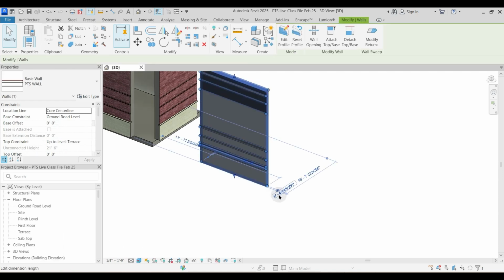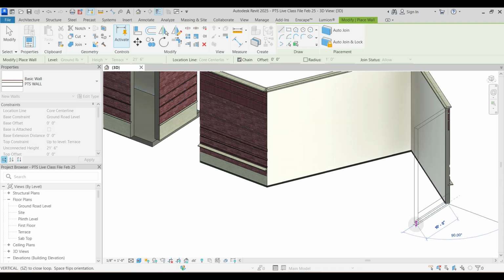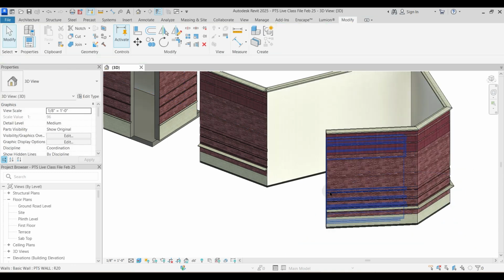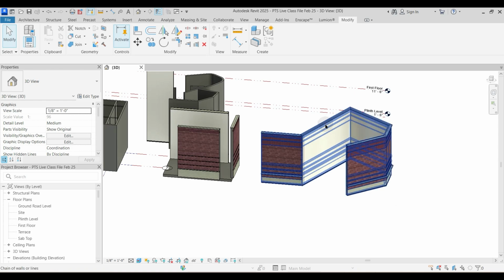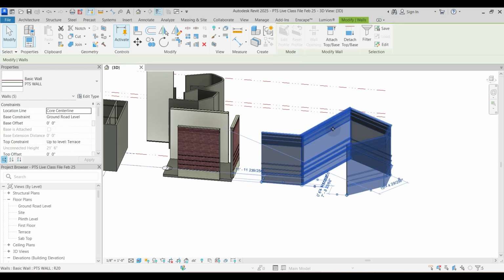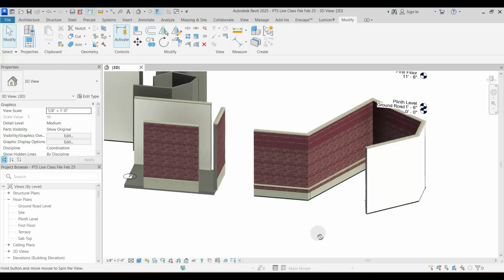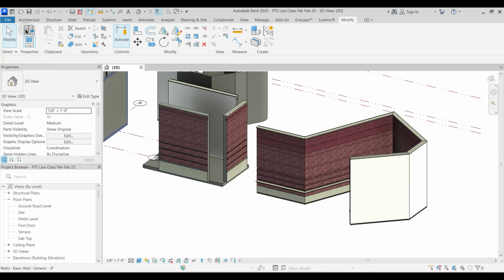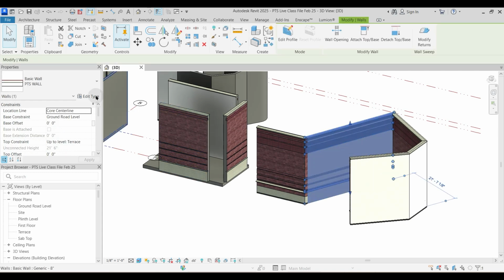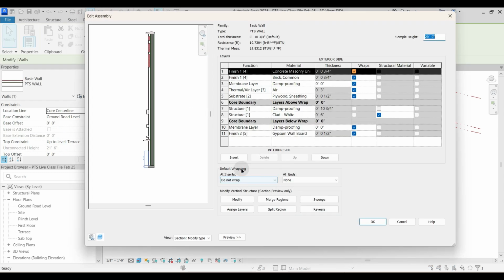With this, if I just say CS, that is create similar, I will just create that wall. Okay, press 1 and tab. So that will select the chain of walls, deselect this and just press space. Okay, clear? Now, what remains here is only this particular thing, which will follow tomorrow: default wrapping at insert and at end.